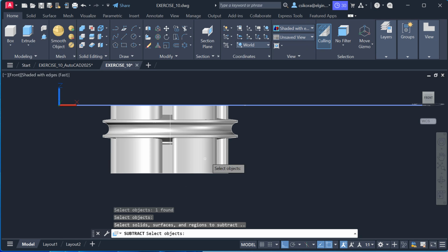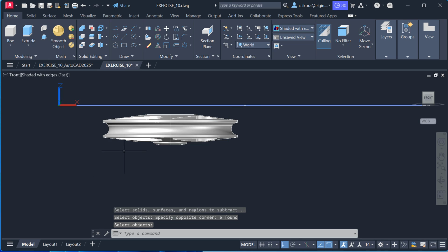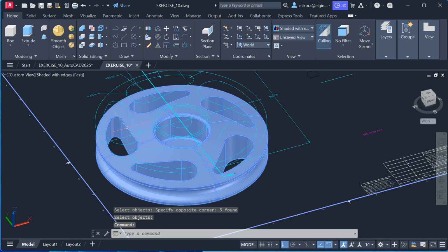And now we want to grab these. So if you go from right to left by clicking and then hover over just the base of this, try not to include the wheel, click, and it should just select those objects below. Then you can hit enter, and now we have our pockets, or our through holes. So now what we're going to do is put in the chamfer.